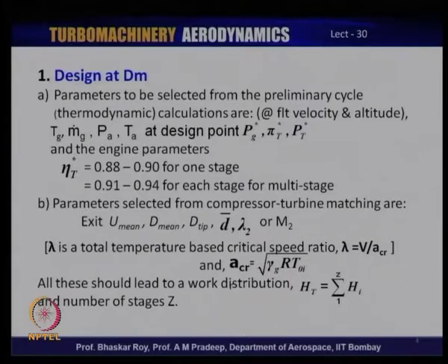and then split between HP and LP, depending on how much power needs to be supplied to the HP compressor and to the LP compressor or fan, and then correspondingly design the LPT and HPT and distribute the work in those stages within the HP and LP turbines. So, that is how the distribution of work is done and the number of stages often arrived at.